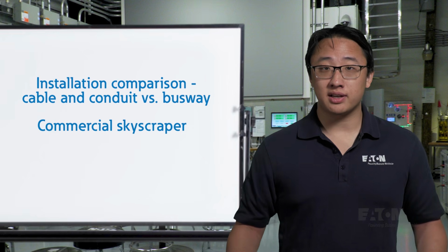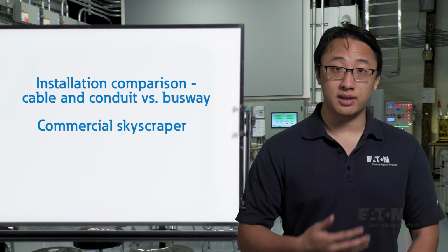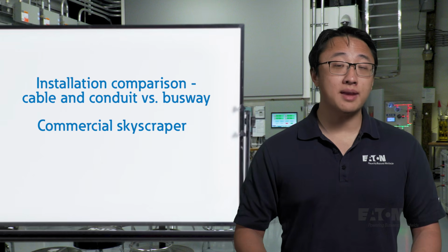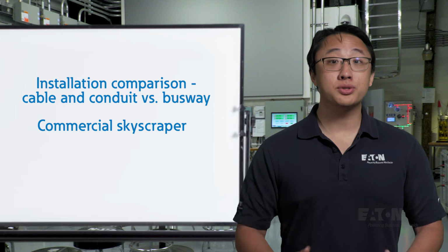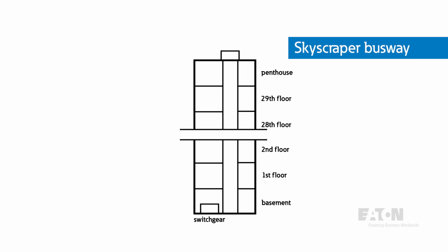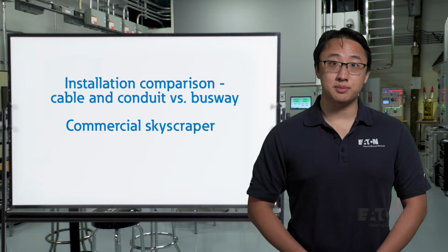Again, especially depending on the amperage required and size and number of cables being pulled, this is a very time and labor intensive process that can multiply very quickly. If we do the installation with busway, instead of running a home run from the basement to each floor, we can simply tap off the busway at each floor, drastically reducing the installation materials and labor. Think of it like using a 480 volt power strip for your entire building. Using sandwich style plug-in busway like Power Wave 3, all that's left to do is install a plug on each floor and connect it to the panel board.